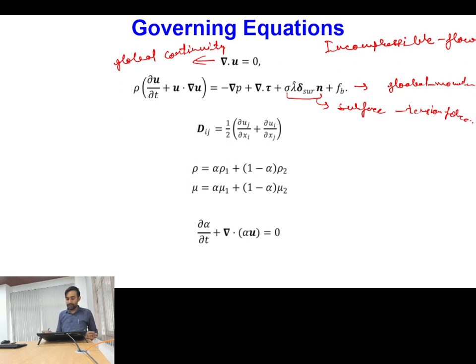So if you see your continuity and momentum equation except for this particular term, these are identical to the normal Navier-Stokes equations for single phase flow. So using the discretization process I have shared with you through these CFD lectures, you will find the discretization of these two equations, but the discretization of this term is missing, which I will discuss in the subsequent slide.